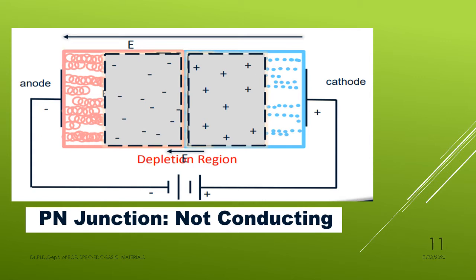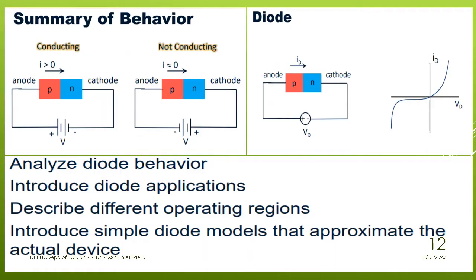That is, whenever the diode is reverse biased, the amount of current passing through the junction we'll call a reverse saturation current. That is also flowing from positive polarity to the negative polarity. Just see here the current direction, from positive polarity to the negative polarity. That is reverse saturation.